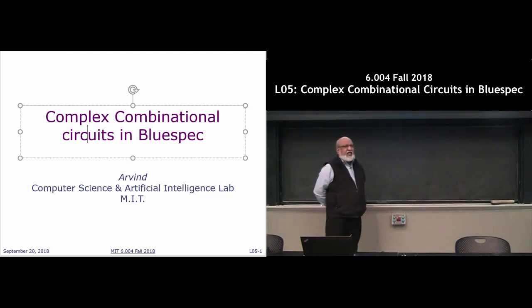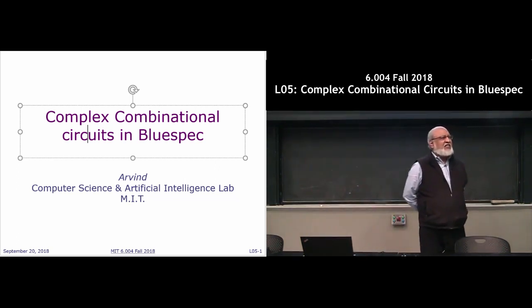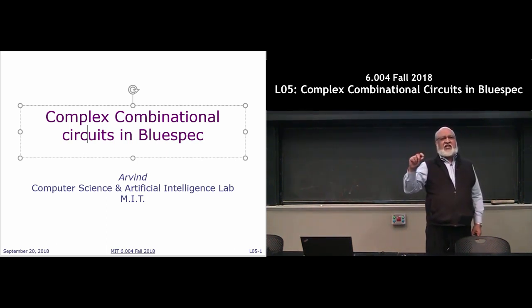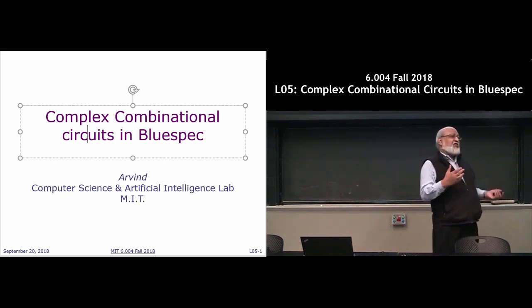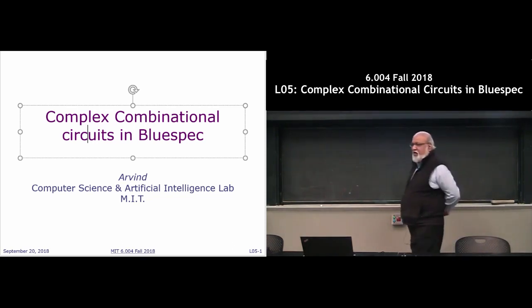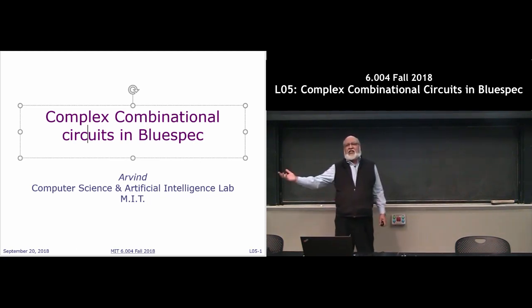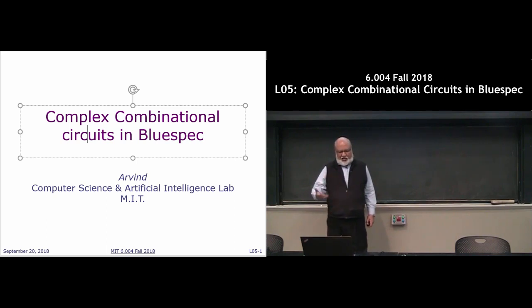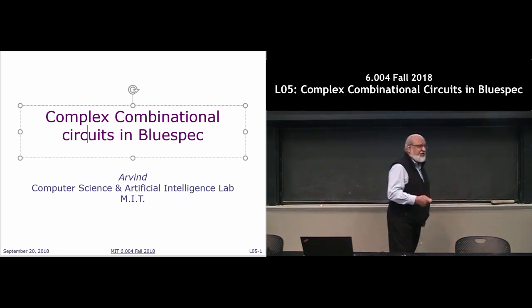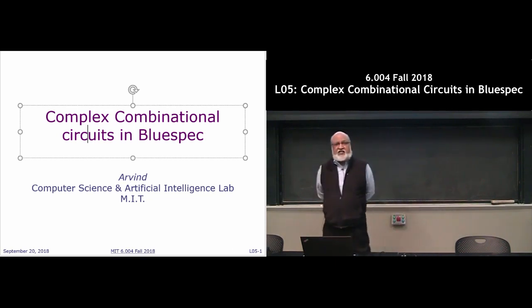So, okay, I have already been using this number sign all over the place, but any time you see this in a type definition, it means it's a parametrized type. That means I can build more interesting types by substituting a value for a variable in there. So look at the example. I write Bit#(n). What that means is that you can substitute any integer for n. So you can write 1, 32, 8, etc. And that's instantiating that type to a very specific type, right? So given Bit#(n), you can make it into Bit#(1) or Bit#(32), etc.